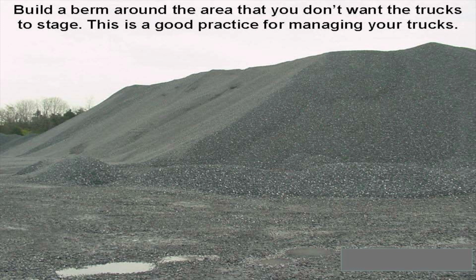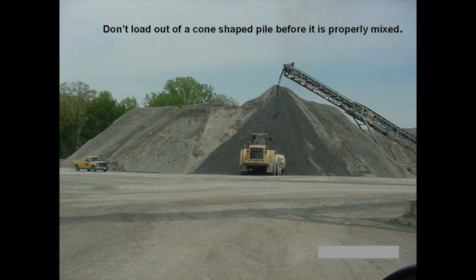Another way to manage the trucks is to build a little berm around your stockpile so they don't park in areas where you can't manage them properly. We've got to be able to direct the trucks because they can really mess up the operation if you don't. They're trying to do their job as efficiently as they can, and we've got to give them all the help we can to make that happen. And again, Trenton talked about this. You don't load directly out of a cone-shaped pile like this because you know you're going to get segregation. And it can be dramatic to where the guys in the quarry can do everything right through the secondary and tertiary, and it's going into the stockpile, and the loader operator doesn't get it out of the stockpile the right way and get it remixed, because we all know it's going to come apart as it goes through that process. We're done.